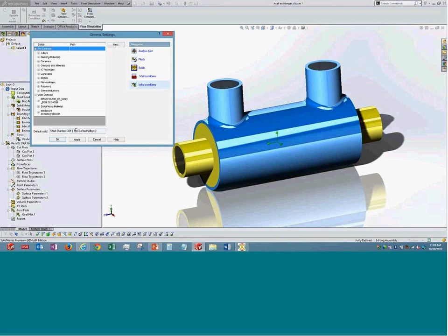So I showed the extra things that were necessary in this setup: we selected the heat conduction option, we selected two fluids, we specified the material of the solid, and we specified the amount of heat that is convected to the atmosphere. So these are the extra things that were necessary to be done in terms of basic input that we start off with to create this setup.